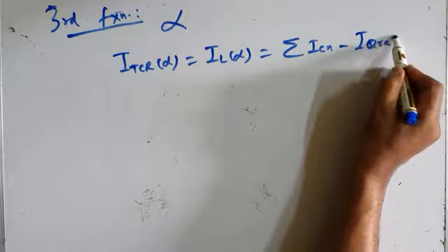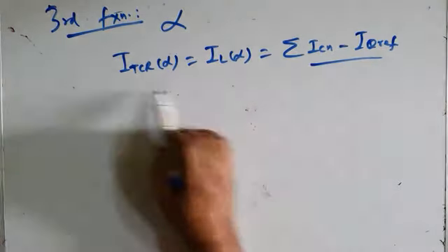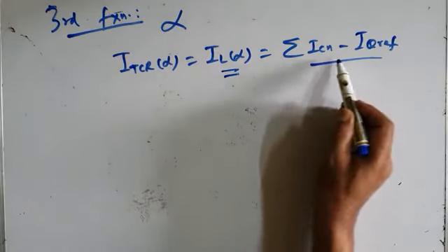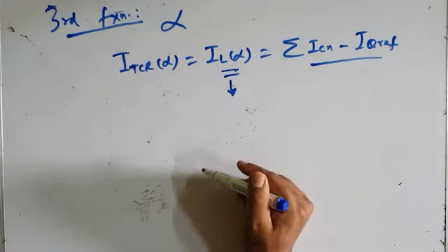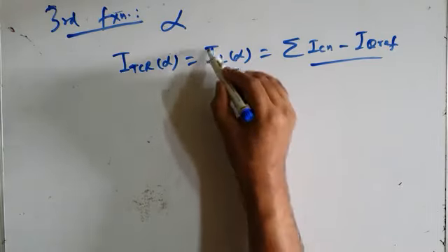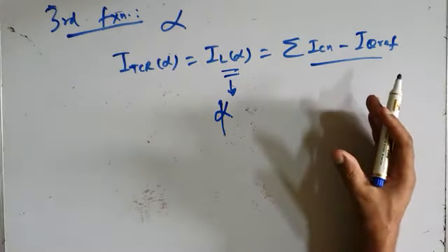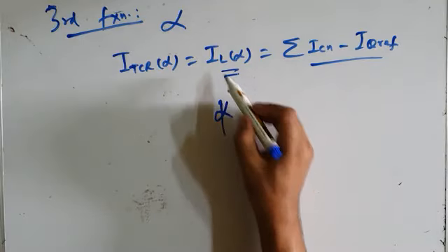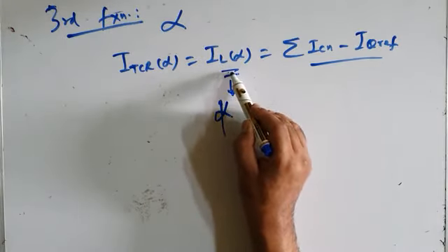IQ ref. This current, in step number 1 itself, your controller has already found how much inductive current is required to cancel the surplus capacitive current. It gives this information to a mathematical block, and that block calculates alpha. Depending upon how much TCR current is required, it calculates alpha and issues firing pulses to the switches of the TCR at the desired value of alpha, so that the surplus capacitive reactive current is cancelled by this inductive current drawn